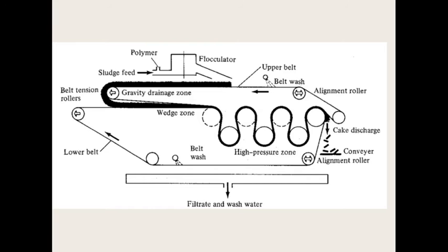Okay, so how to convert sludge to an energy system. Before that, we discussed anaerobic sludge digestion, thickening of sludge, stabilization of sludge, conditioning of sludge, dewatering of sludge, hygienation of sludge, and sludge drying bed. So how to convert sludge to an energy system? That is nothing but anaerobic digestion. What is the first step? Collection of sludge from the wastewater. The next stage is thermal hydrolysis. Next, anaerobic digestion.